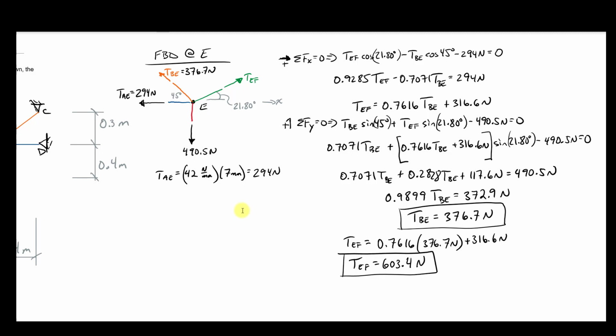These are all positive. They're all tension. Since they're positive, two things. One is when you draw these free bodies, always draw your unknown vectors pointing away from the particle, because that means that you're assuming a tension which is pulling on the particle. All these things are pulling at E. They're all tugging at E, wanting to move it away.